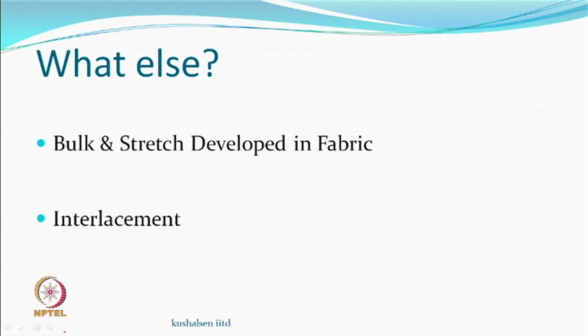What you are doing is very highly twisted yarns have been woven in a light GSM kind of environment, and whenever they get a chance, because of their energy reduction, they want to go to a stable state. So, the crimped or twisted yarns want to come back. One can make crepe-on fabrics, where one set of yarn has one twist, the other set has another twist, and you get beautiful, bulky effects.